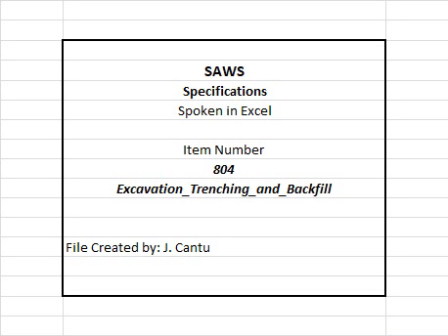D. Where a trench has been improperly backfilled, or settlement occurs, the identified section shall be excavated to the trench depth and a length 50 feet in both directions of the failed area, then refilled and compacted to the grade and compaction level required. E. Safety devices. The contractor shall provide and maintain barricades, flags, road flares, and other safety devices as required by local, state, and federal codes and ordinances and conduct work to create a minimum inconvenience to the public. F. Temporary suspension of work does not relieve contractor's responsibility of the above requirements. G. Safety and health regulations.